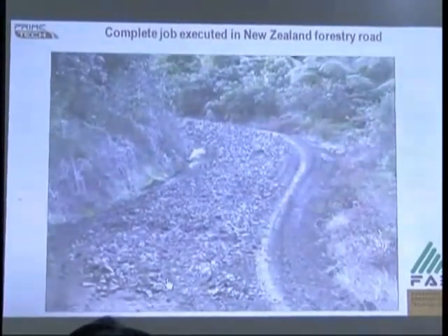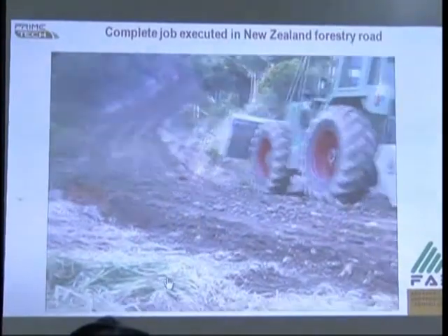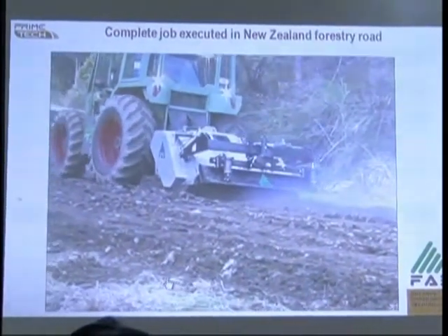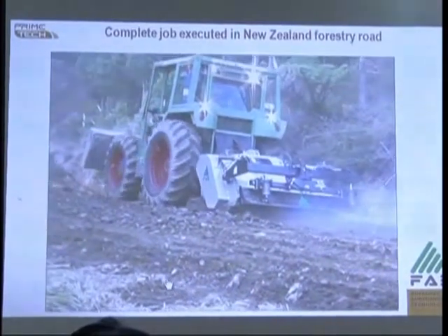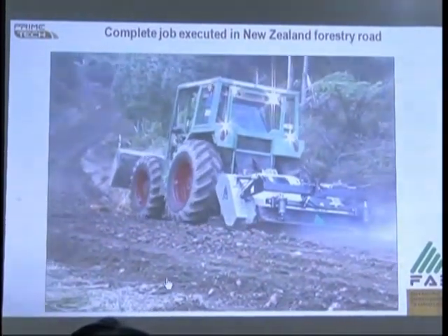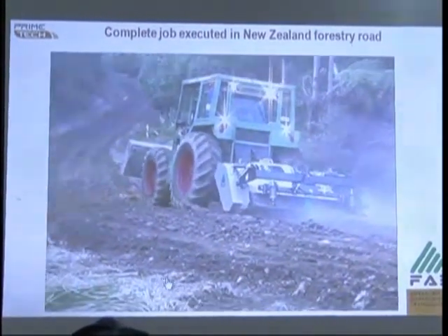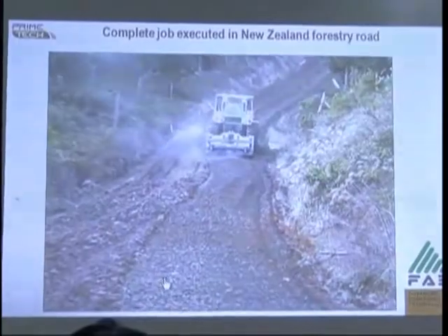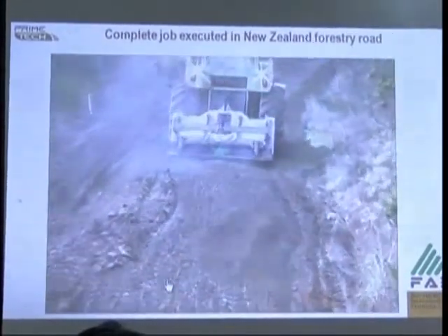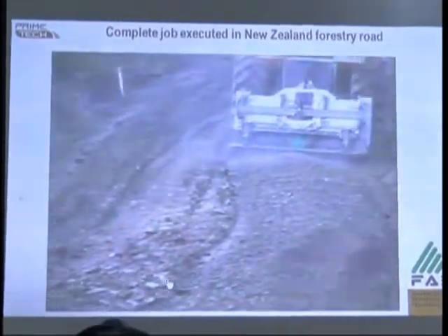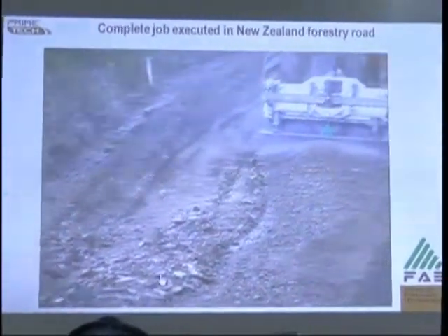They added water here, because it's also important to have a good amount of water. On your roads I saw there was a lot of water, but water is important because water acts like a binder, keeps everything together, like a glue a little bit. So in this case they just crushed, shaped with the grader, put water and vibrating roller. Very simple job. Very cheap.